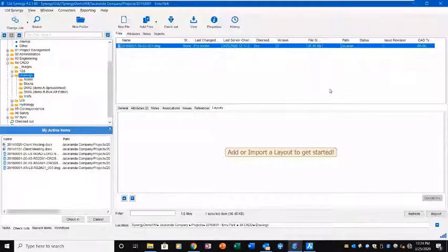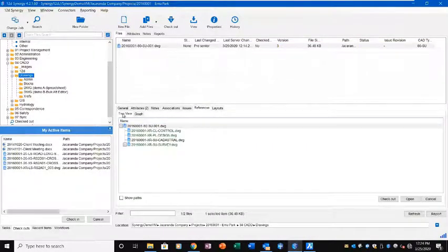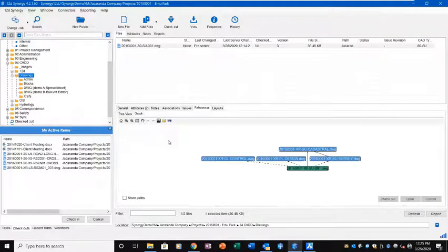The other thing you've got is your reference tree. So you can use it as a tree view. So this tells you what Xrefs are now in the drawing. Green one's been overlay, the black one's being attached, or you can use the graph like the diagram I showed you before. So again, dashed lines representing overlays, solid line representing the attachment path.